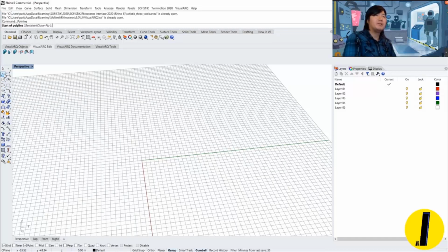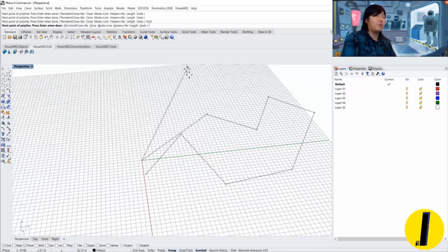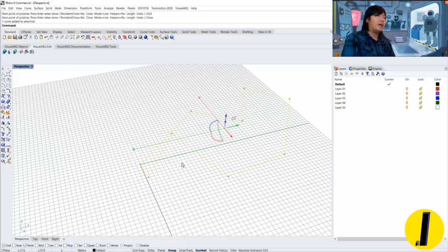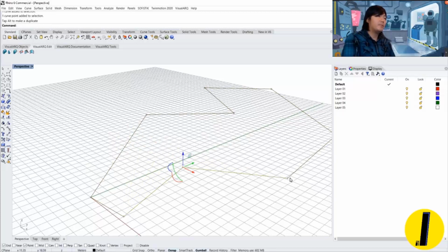Just a very simple example. I'm going to click on this polyline. I can put in any points, or you can also give the coordinates here. For example, you can put 0,0,0 and it goes back to the exact point. Here we have multiple options to close; for example, if I leave it closed, then the line is closed. For now, this is exactly the same as AutoCAD, and you can click on the control point of the segment and update the line geometry.